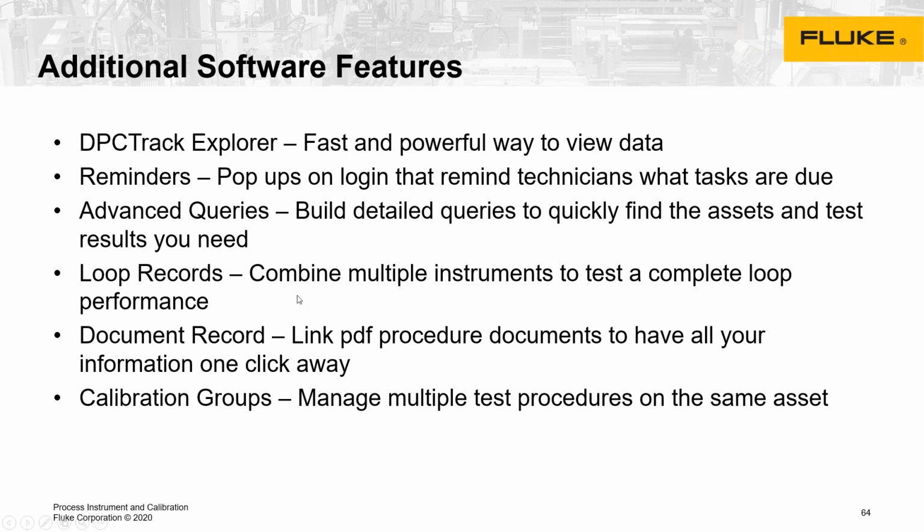Loop records allow you to combine multiple instruments into a complete loop. So if we have a multi-drop loop or multiple assets, a switch that's tied to a control valve, we might want to calibrate those together. You're able to pull those together into loops.